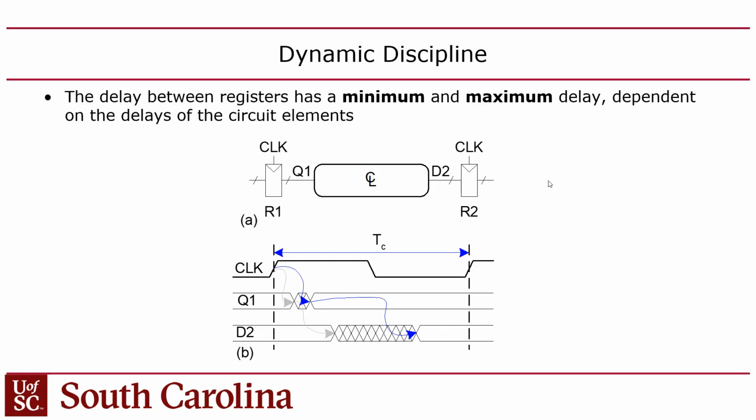For example, that first flip-flop is, for example, your instruction underscore EX, right? And the instruction underscore EX has to go through your control unit. Your control unit is combinational logic, and then your control unit generates basically a write enable signal, right? That gets clocked into a pipeline register for write enable, right? So that is one such path. Now, of course, there's a bunch of those paths in parallel.